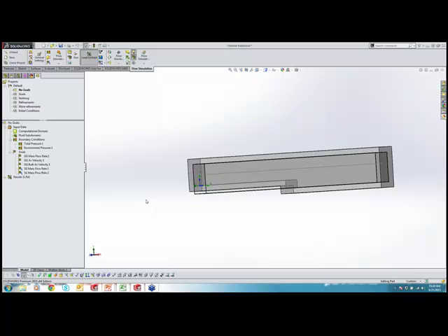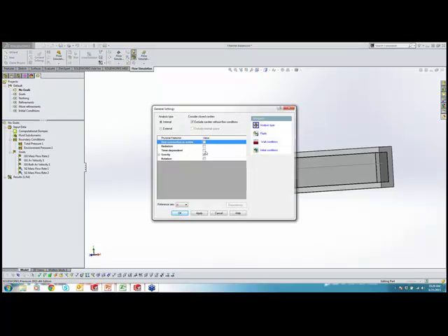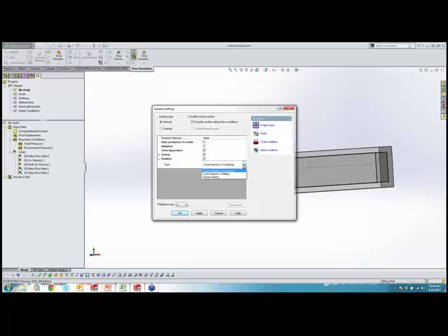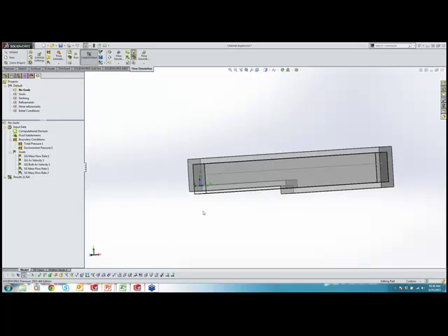And then by solving it with a transient analysis, the time dependency one, where you can add time steps, you can tell it, with rotation enabled, yes, I know, and we use the sliding, we can have one piece of the valve move and have a really fine time step to capture the valve start from closed and move to open. Okay. So having a physically translating boundary is difficult.